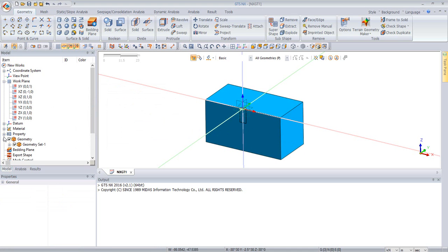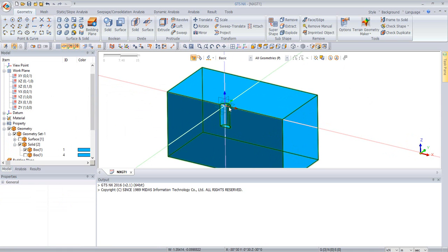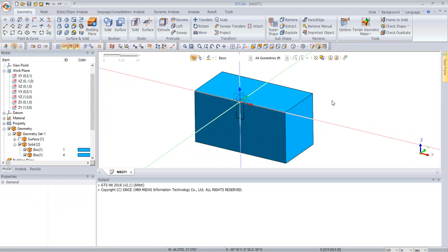And now it's a more realistic interaction. If I deactivate the surfaces and deactivate one of the solids, we see that the program now recognizes that they're not going to overlap. One is indeed inside the other. So now what I'm going to do is use a command we have called mirror, just to basically reflect this and make a full 3D. So that's another point of departure from the Plaxis tutorial.